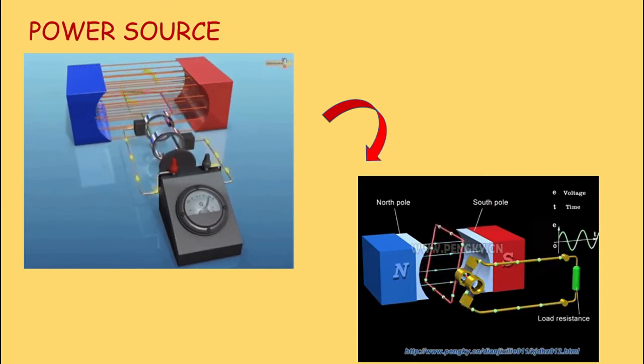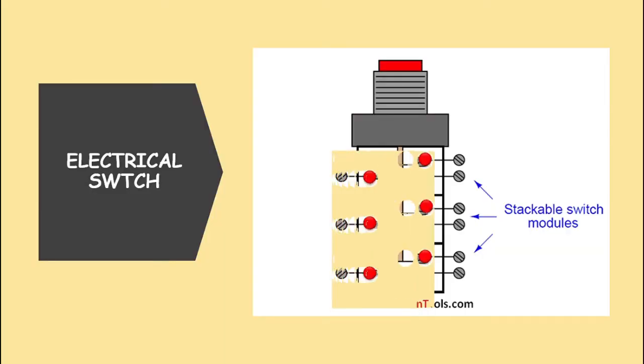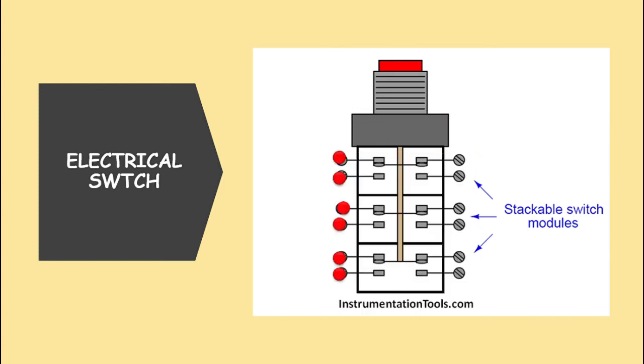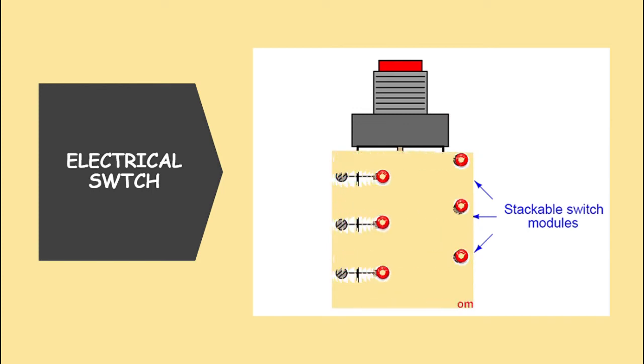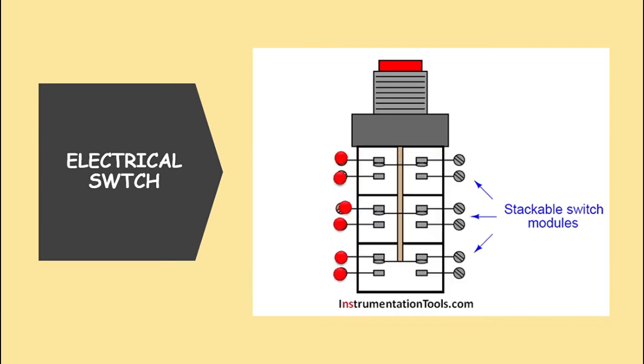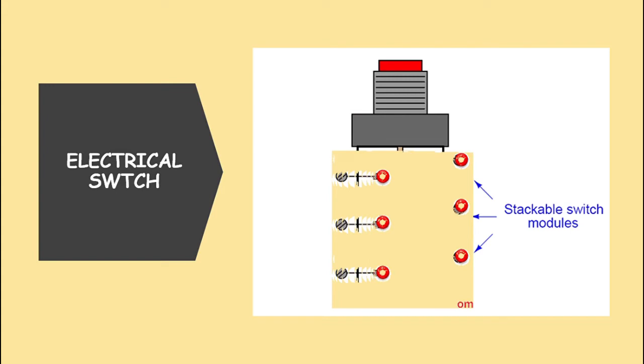A simplified circuit for generating exponential decay pulses is shown. It consists of a charging and a discharging unit. So, in the charging unit, an electricity storage device is charged across a charging resistor by a DC high voltage power supply. So, the generation of PEF requires slow charging and rapid discharging of the energy, as the pulse width is short in comparison with the time between pulses.